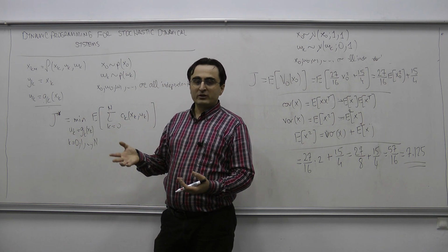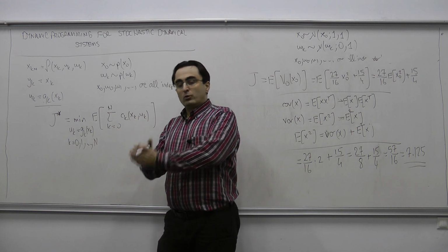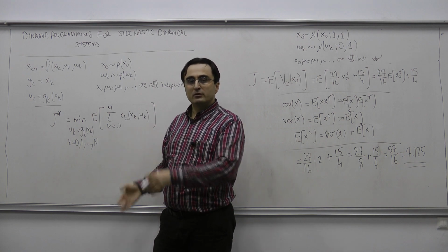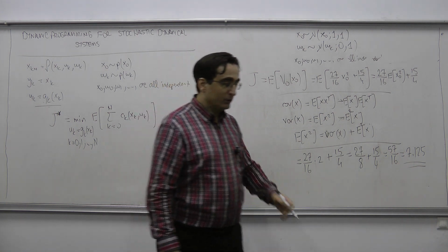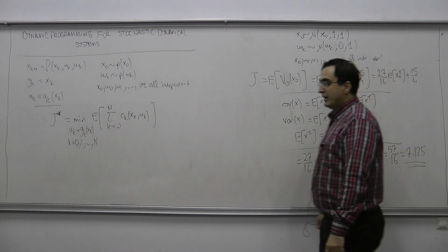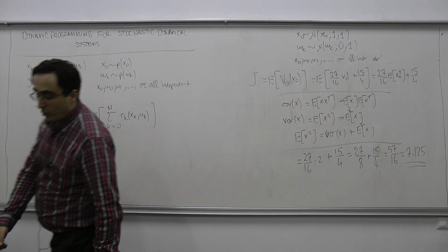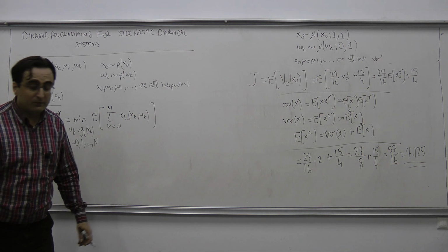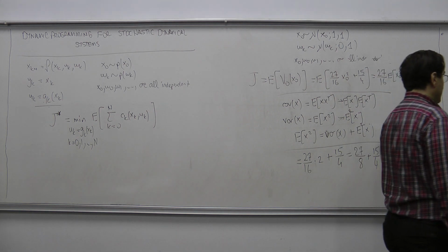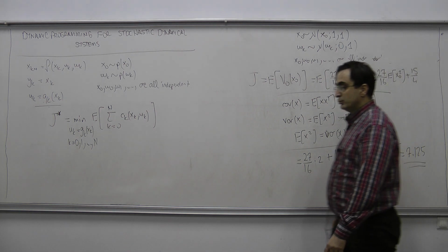And then after doing that optimization, we are going to go one step back, and we are going to do the optimization with respect to the new or the previous input variables, and that is going to give us at the end the optimal strategy or the optimal feedback policy, which is usually non-stationary. So at each time step, we're going to get a different input feedback rule.